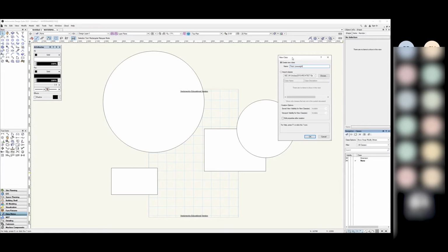And obviously the line weights that you choose depend on the scale of the drawing you're printing out and the page size. So for instance, if I'm printing out a drawing on an A4 piece of paper, if I were to use super thick line weights, it's going to look like a really messy, heavy drawing. Whereas if I use slightly thinner ones, it's going to look much nicer and a bit cleaner. If I were to use those same thin, clean line weights on a massive A0 printout, I'm not going to be able to differentiate between them, because the object is now so much bigger, but the line weights are still essentially the same. So using thicker line weights on a bigger sheet would make more sense. So there's no right or wrong which line weights you choose, but you should always use a doubling factor.